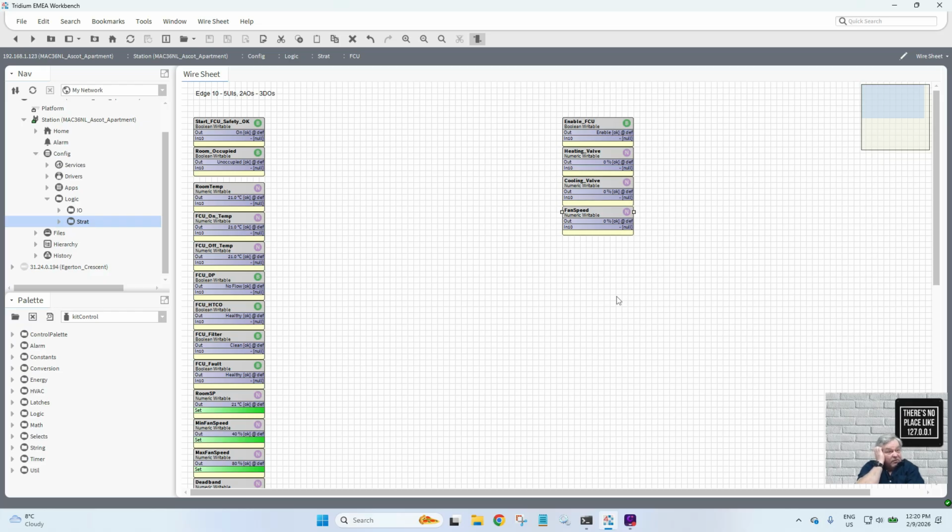But sometimes you can just buy fan coils which haven't got a controller in, and you've got a 0 to 10 for the speed, you've got a fan enable, and then you've got your valves there for 4-port with your cooling and your heating, and then you've got to write your own software.